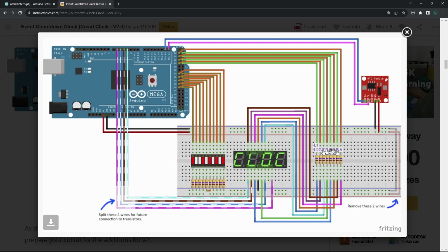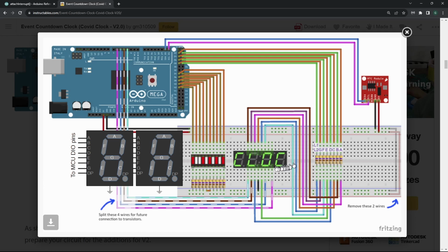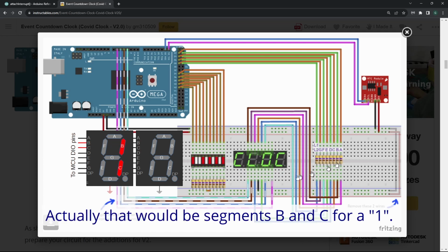And then you keep outputting digits very quickly in succession, so this one, then this one, then this one, and then this one, and you update the selector to make sure that it's just displaying that one. So if you want to display 1, 2, 3, 4, you could output 1, which would be A and B high, and then pull this one low with the rest being high.